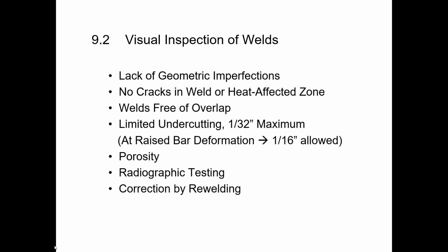You want it to be consistent shape and size and location. You're looking for cracks in the weld or in the heat affected zone of the base material or bar. So you obviously don't want any imperfections, don't want any cracks. You want to make sure those welds are free of overlap. I'll show you a diagram in just a minute. I think it's right here. I'll flip to that slide in just a second.